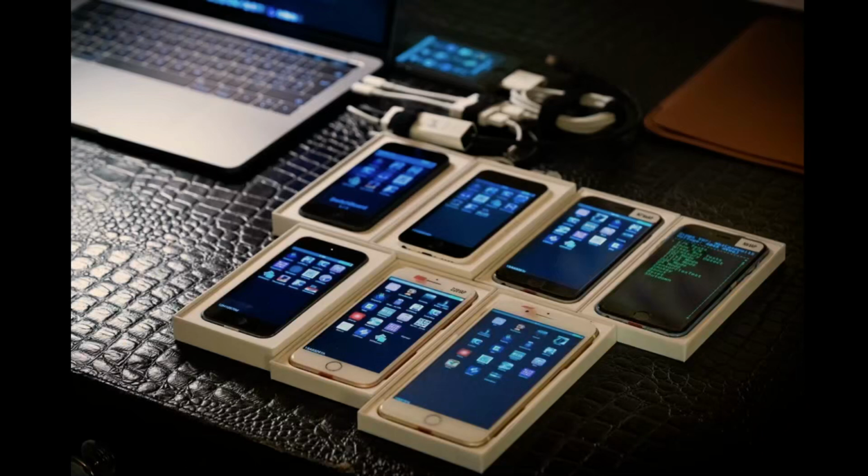And that's the thing called dev-fused devices, development-fused devices, prototype iPhones. These are all names for a similar concept, which is a type of iPhone that has extra debug capabilities built into it. So that's things like serial wire debug, JTAG, basically functionality that allows you to debug the phone at a very low level.